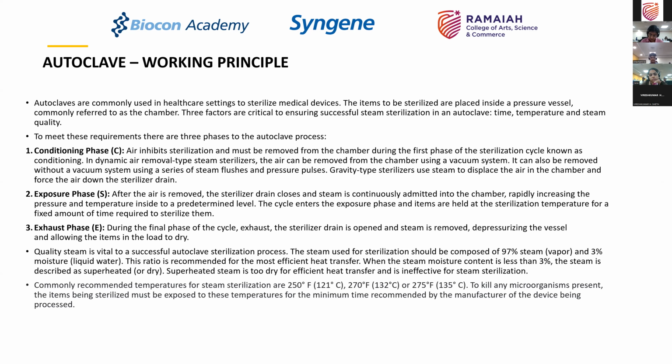And therefore, you always define a range at which you are going to do the autoclaving, and not a single item. So if 121 was the temperature at which your FO values were established, then you define a range around it in centigrade. So at no given condition does my temperature go below 121, and it is not overheated, so that I end up with too much of an overkill, or burn out the products. So you will always define a temperature range at which you are doing autoclaving, and a pressure range at which you are doing autoclaving.